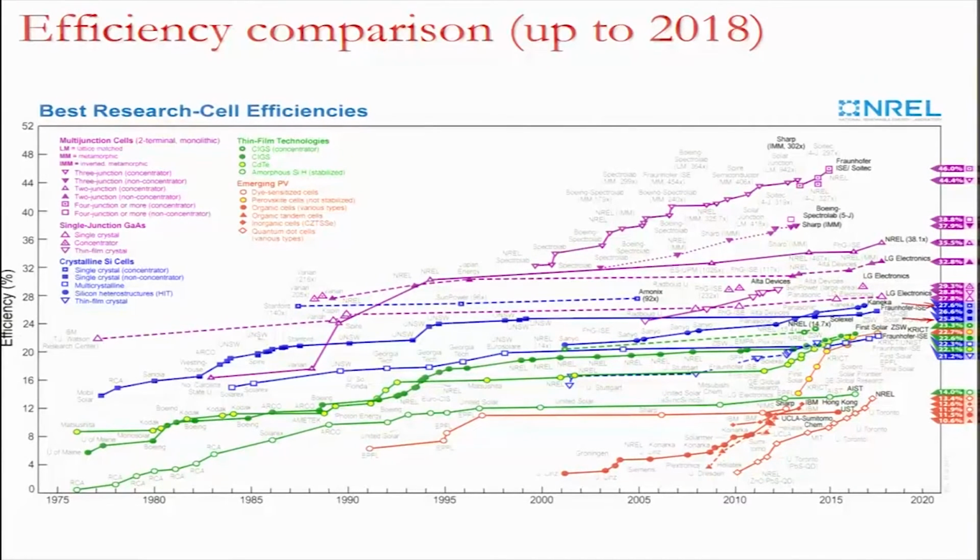And if you go to thin film technologies, the ones in the green, the CIGS has a number of about 23% right now, laboratory scale, in the concentrator mode. If you go to non-concentrator mode, the efficiency is about 22.6%, which is here. And cadmium telluride is about 22.1%. These are laboratory best efficiencies, but these are not the average efficiencies. These are the world records in that sense. And then amorphous silicon lies low at 14%, and the work on amorphous silicon has almost stopped now.